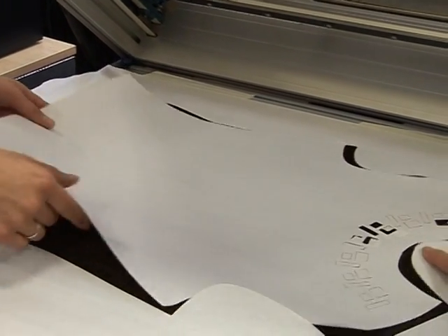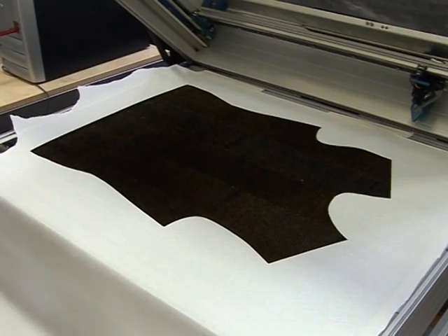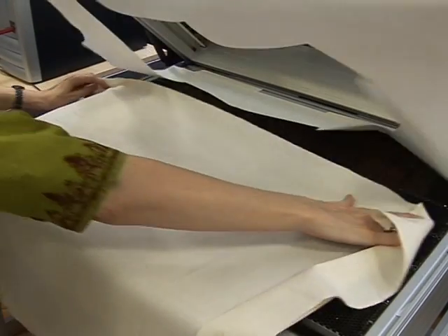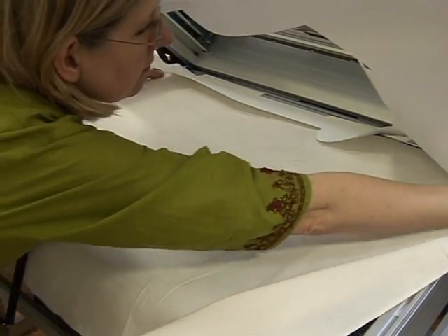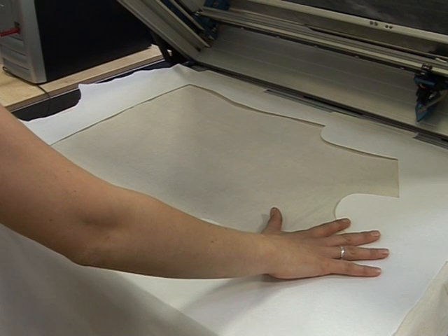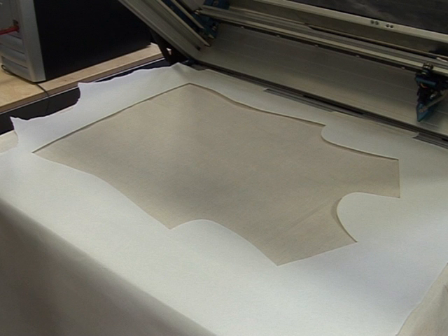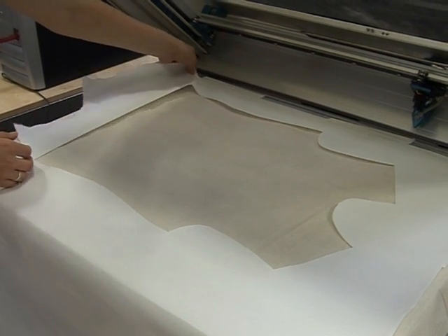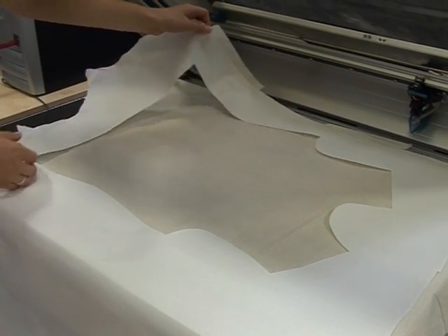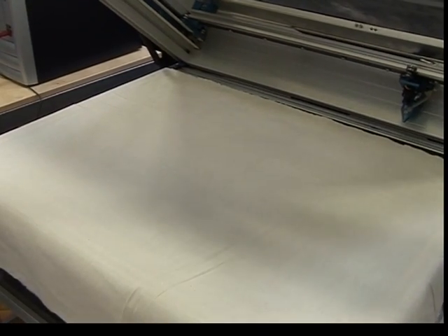When the cutting is complete, lift the lid carefully and remove the cut paper shape from the background area. Lift back the paper, being careful not to move the masking tape holding down the far edge, and slide the fabric that you wish to use underneath the paper. Use the paper as a stencil to position the fabric underneath. Whatever you can see in the cut-out sections of the paper will be cut out of the fabric. When you are happy with the position, tape down the fabric and remove the paper. Close the cover gently.